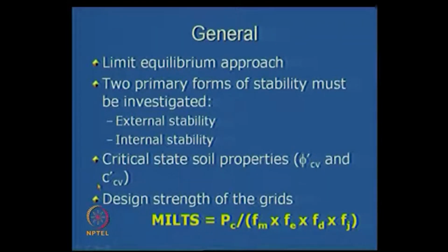These shear strength parameters should be obtained corresponding to large strains. This is what we saw in reinforced slopes also, that we conduct a direct shear test or a triaxial test, say a better triaxial test, in which you get c and phi as effective stress parameters, for 3 or 4 normal stresses, and then you get c and phi from these large strains.